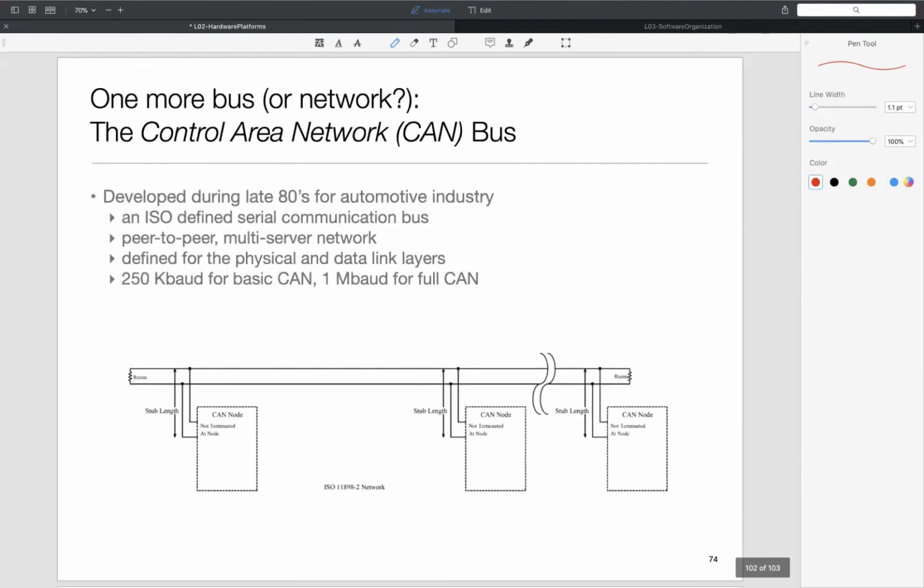So the final one before I stop for the day is this Controller Area Network. The reason I want to mention this is because if you want to do any project involving your car, it is very easy to interface and pull information from the car. You might have seen these gizmos you can buy which attach to the OBD2 port on your car, so that's the CAN bus. But another interest is that it's an example of a multi-master bus with a particular arbitration protocol, which is interesting.